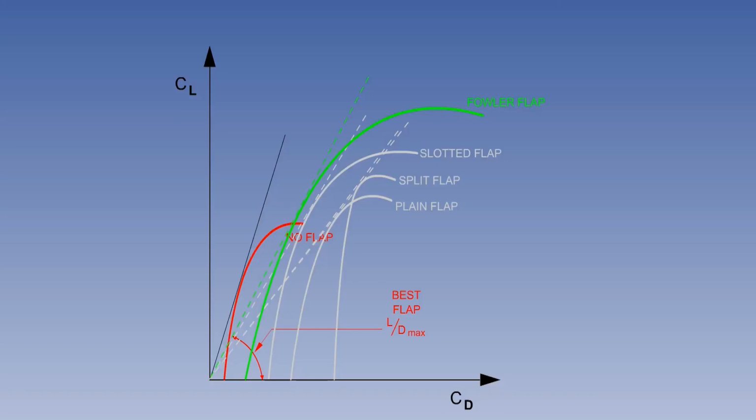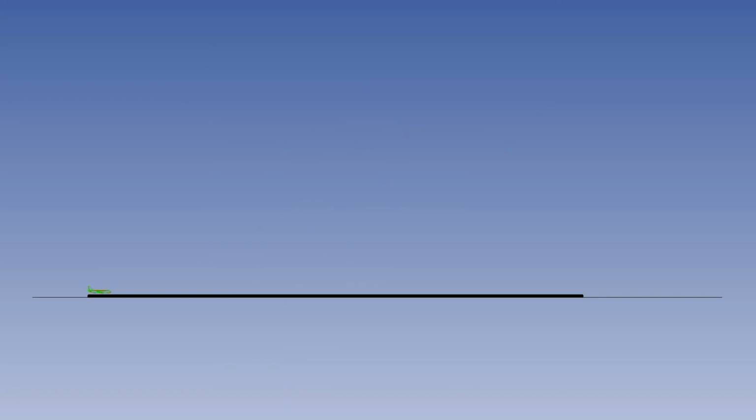Does an understanding of reduced LD max with flaps down have a practical application? Yes, it is a very important takeoff climb consideration. We have learned that the use of about 15 degrees of flap reduces the takeoff run. That's why flaps are fitted. But any amount of flap reduces the ability to climb.